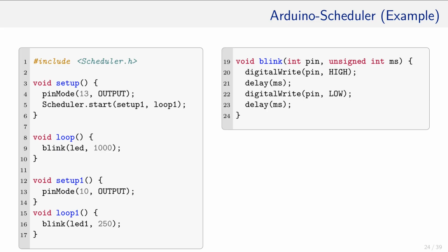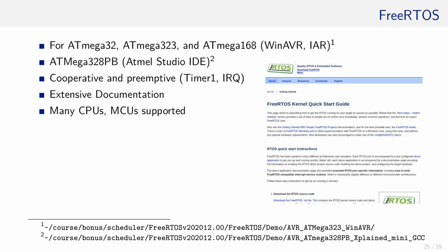Where is the part that we said is required for the task to tell the scheduler to consider other tasks? It is hidden in the delay call, which contains a call to the function yield. By including scheduler.h, the yield function has additional functionality, as we will see in the second half of this chapter. First, let's have a brief look at other schedulers.